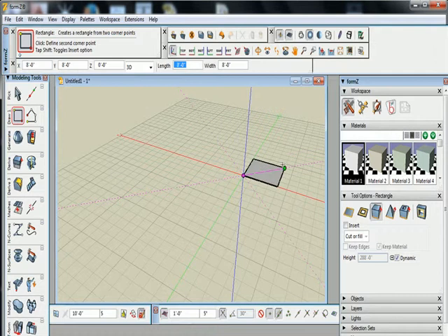Okay, so you can use your snap setting and try to find a section that says 18 foot length, 18 width. For some of us it's a little difficult to do. I don't know if we just don't have the accuracy to operate the mouse that way. But in that case, right where it says length, notice that the number is in blue, right here. So in length, we type in 18 foot.